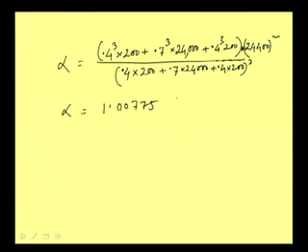Okay. Like that, we can also calculate for beta. What I want to emphasize is that when we calculate a value of alpha for a particular channel section, and if we use the same alpha when it is in flooding condition or when it is in a very lean period, these two should not be the same, it will be different. So, we should be careful in using this value. We should know what the practical significance is.